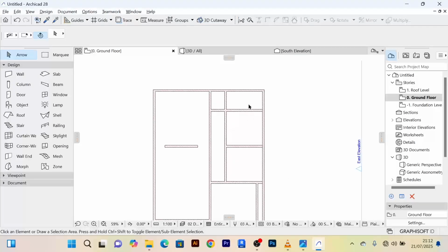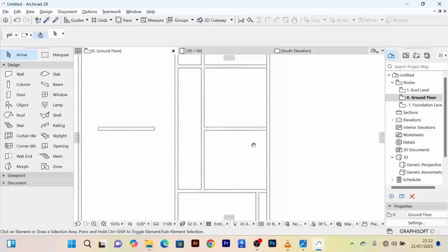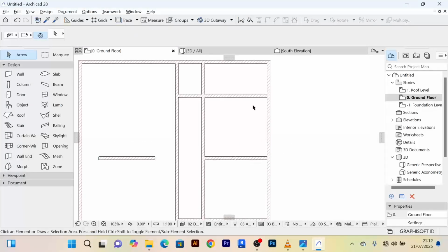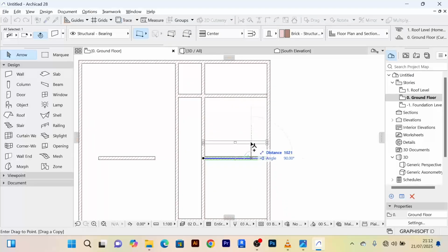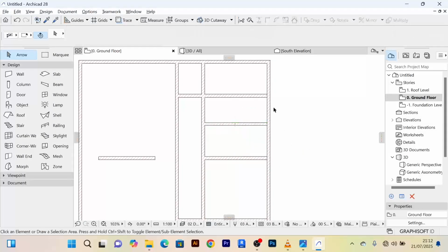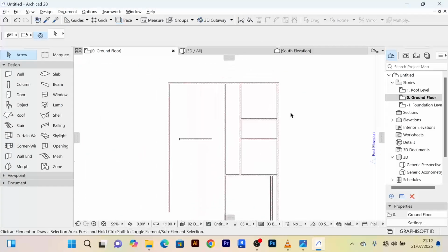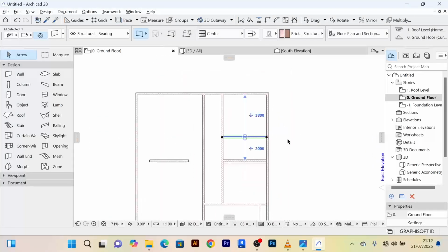So this room that we have created here should be in the middle here. So I'm going to offset this by, let me see there, 2 meters. So I'll Control Shift D, I'll drag it by 2.2. That will give us 2 meters. Then I can simply delete off this, because we don't need it now. So we now have this as our common washroom.